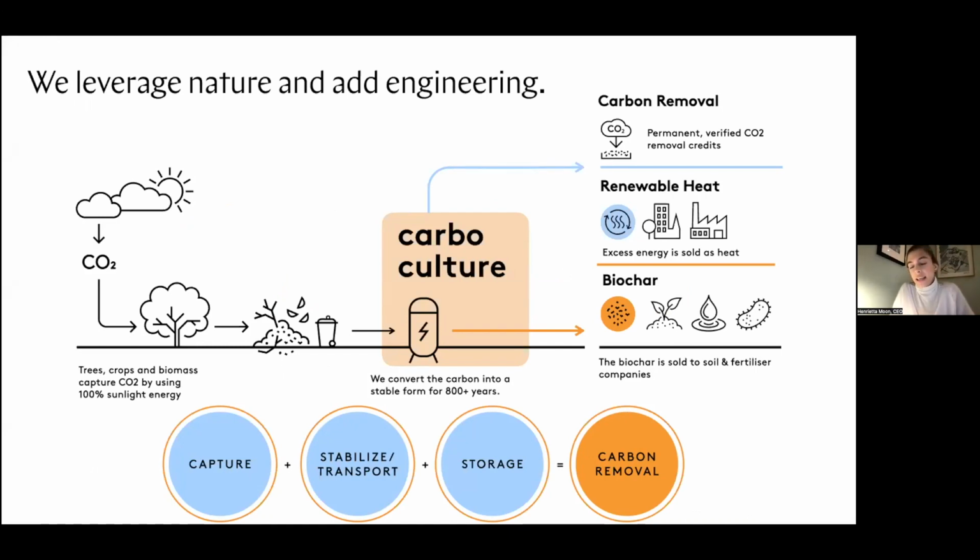And this leads to an exothermic reaction. So if you're thinking about the reactor like this, we actually go through the material in a way that we combust through it. And this way we get to high temperatures, which lead to high permanence, high purity, and so forth. And instead of making bio oils and biochar, we actually only generate the solid material, which is the biochar, the biocarbon, very clean. So, 80–90% fixed carbon.